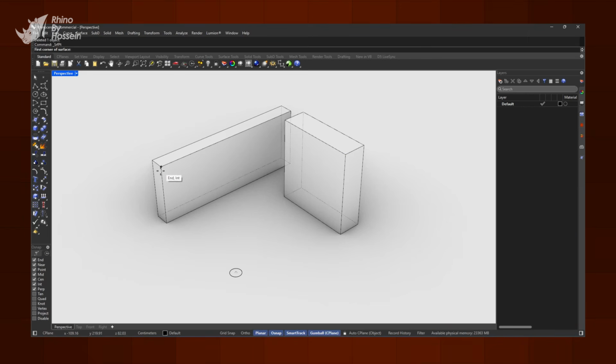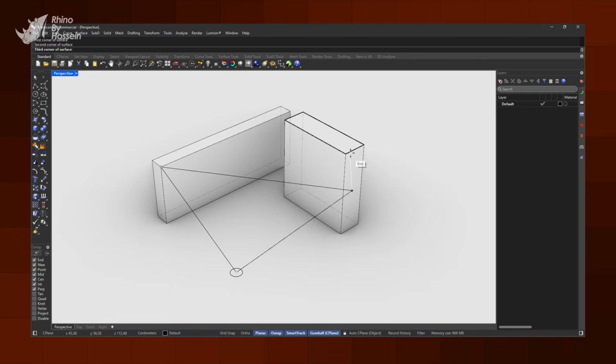If the curve isn't truly planar, Rhino can't interpret it correctly, and the result can be twisted surfaces, inconsistencies, or unexpected geometric errors. This becomes especially critical in architectural work, where many forms need to be clean, precise, and actually buildable. The solution is simple.